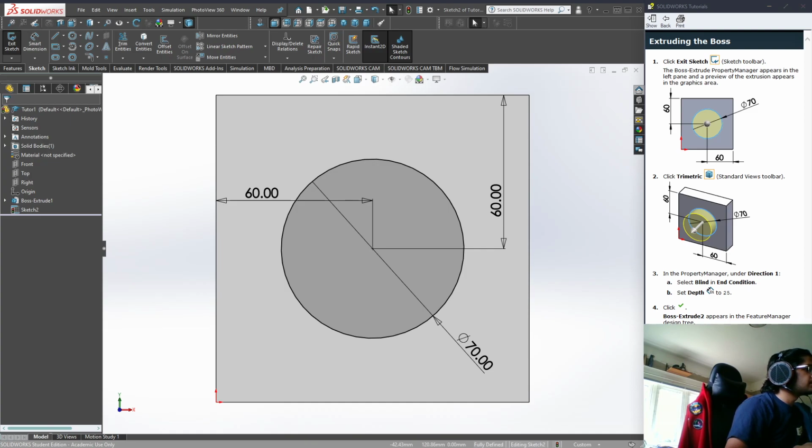Oh, so now can I recenter the circle? No, double click. Yeah, it should join the sketch. Or, okay, try right clicking it and clicking that edit sketch button. It's the very first icon on the top left. Higher. Yeah, there you go. Okay, so now you have your editable sketch. So if you want to make edits to it, that's how you get back to it.